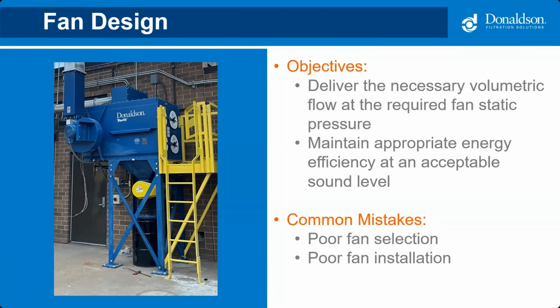Secondly, the fan you selected should be able to deliver the desired static and airflow with appropriate energy efficiency at an acceptable sound level. Fan challenges generally fall into two categories: poor selection or poor installation.